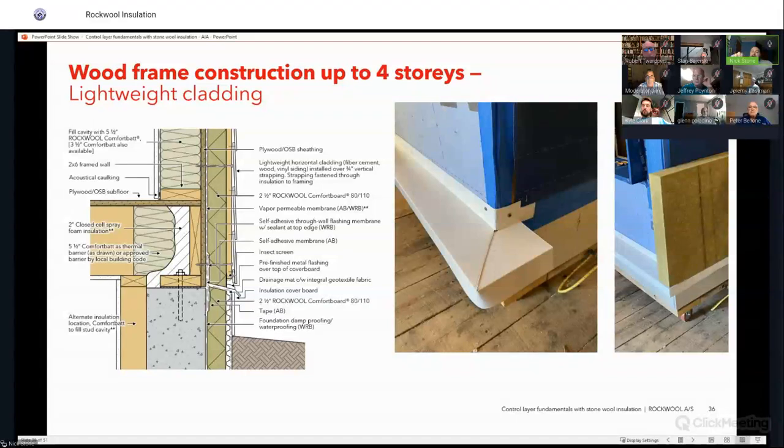And then inside my framing, putting a dab or a dollop like their nails and taking a J roller and rolling them all in. I'm a huge fan of that. I think it makes a really nice solid system. So you have no fasteners passing into your vapor barrier. You just have so much more continuity that way to really create a very effective system that's not going to allow vapor to pass into that area.